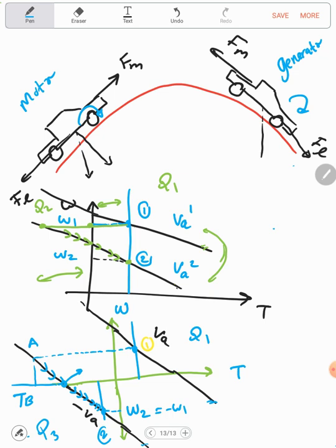This is also another method that we will enter to the regenerative braking, which means that in general, if I'm using the machine as a prime mover, as drive, it's not my intention to operate the machine as a generator, but I need the machine to operate as a generator in order to allow the power flow to go from the machine to the supply if there's an extra power, or if there's a generated power in the machine that I can recover.